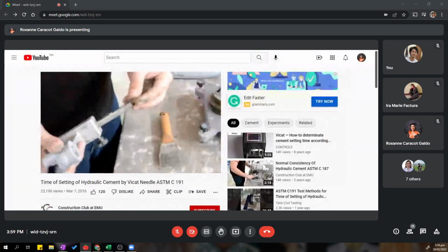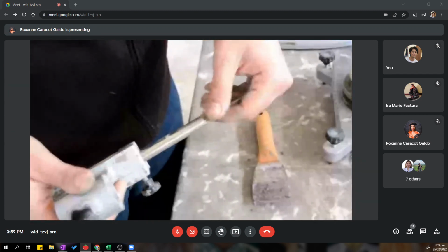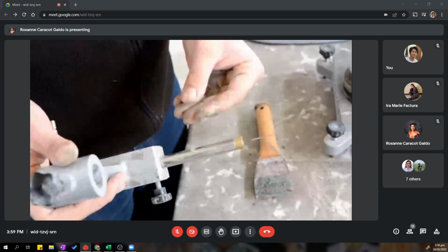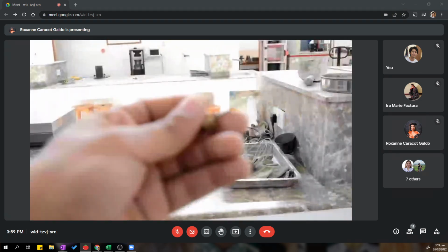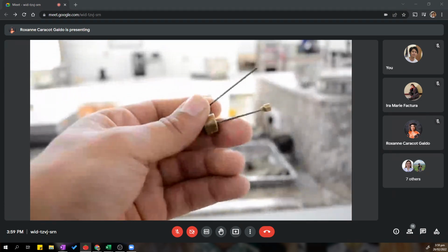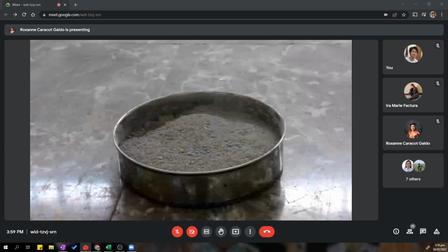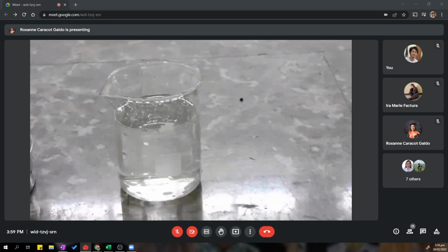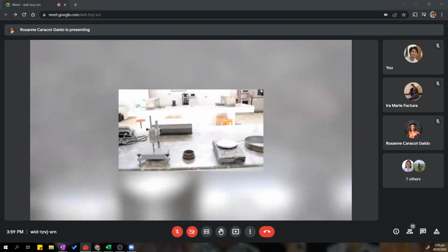In this video, we will cover setting time of hydraulic cement by VICAT needle. In other words, the time that cement needs to react or hydrate completely with water. In order to perform this test, you need the following: the VICAT apparatus, 2 needles, thick and thin one, a mixer, a timer, 650 grams of cement, and a defined amount of water, which has been determined by the normal consistency test, which we had covered in a previous video. Click here or on the link in the description box to see the video.